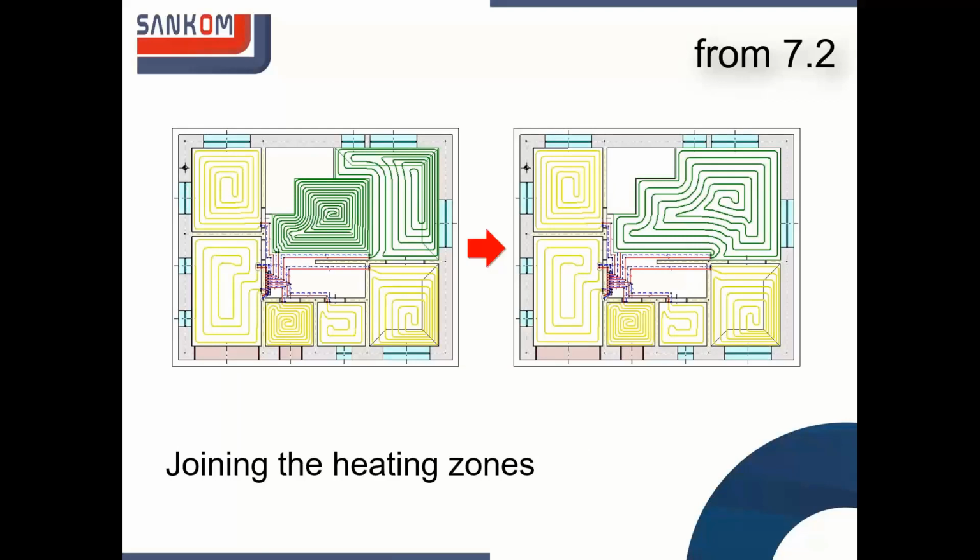We also extended the possibility of designing underfloor heating systems because in the case of these systems, very often you have to change something. For example, if it occurs that the coil is too long because of the pipelines or the resistance, you have to divide it or sometimes join it. So we added these options to make it easier.